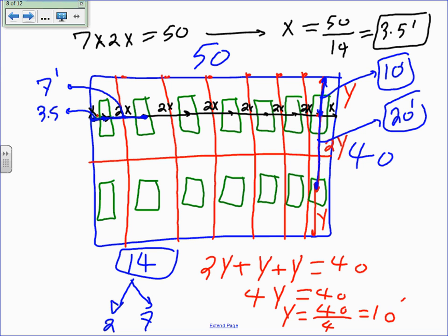Okay, take this. Now I have a 50 by 40 area, and I'm going to orient them. The code says the best distribution for fixtures, guys, is if the distance from the wall to the fixture is half the distance between the 2 fixtures. Look at these. From the wall to the fixture is x, between the 2 fixtures is 2x. Or if this is x, this will be half an x. That's the best distribution to get even distribution of foot candle.